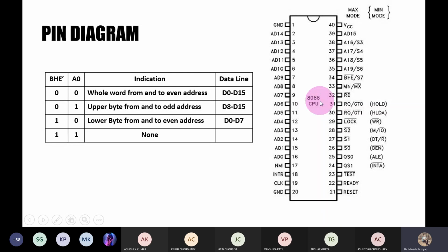So for those calculations, you have to write some specific programs in 8086. And for these basic programs, if you keep on writing functions or subroutines, then most of the time of 8086 will be gone in doing math calculations. So on that note, we use a coprocessor called 8087, which is very well equipped to perform these math operations in a very limited amount of time.